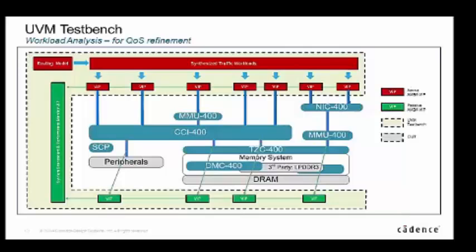DDR's complex because you want to probably also do what's the performance with in-bank hits, in-row hits, in-column hits, out-of-bank hits, right? The DDR is so sensitive to address patterns that it is crucial as well, and we're building some DDR efficiency tests as the next thing we're adding, simply because that's another whole raft of tests that you need to give some sense of what's the best you can achieve. You don't know when your software is executing whether you're going to happen to hit a refresh or not, so you want some realism in there. DDR is a very complex question.